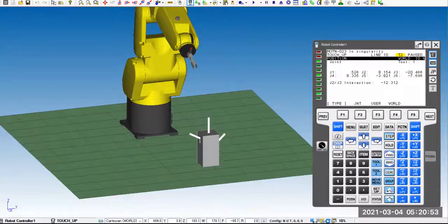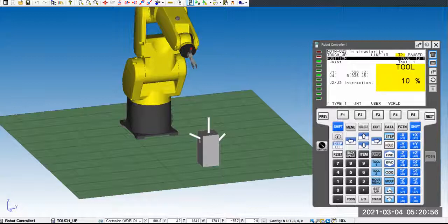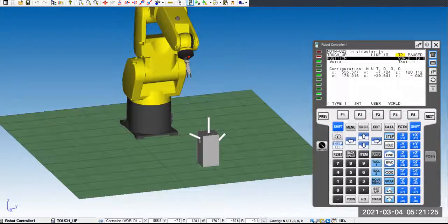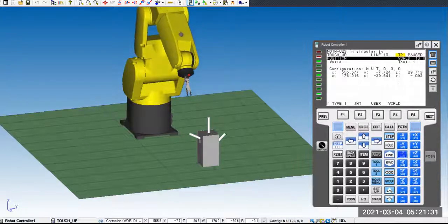So to do that, we have to click the coordinate to change to joint. Oh, I passed it, joint. With J5, change to a different angle. So this is J5, and I want to have a bigger angle here, right? So now I'm at -30. If I go back to world, before I try to lower the Z, let's see if you can lower the Z now. Yes, very good, right? So now I'm getting close.